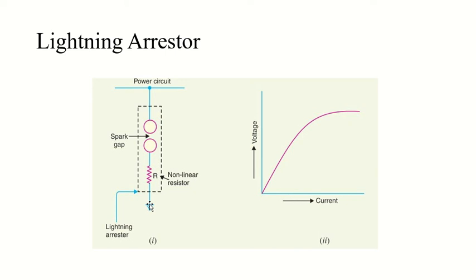Then the function of the non-linear resistor in the operation of the arrestor is very important. As the gap sparks over due to the overvoltages, the arc would be short circuited on the power system and may cause power follow current in the arrestor. And since the characteristic of this resistor is to offer high resistance to the high voltages, it prevents the effect of a short circuit. Once the surge is over, the resistor offers high resistance to make the gap non-conducting. So it is pretty much straightforward.